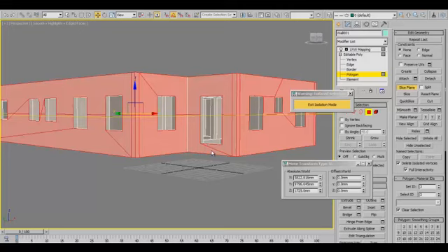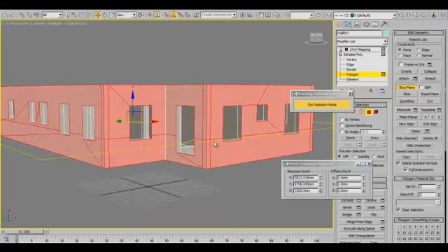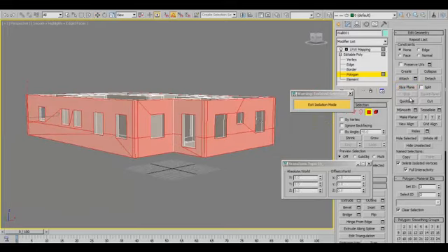This is at a 1.7 height here, so we're going to move it to 1.2, and I think that is good for us. To cut that through, because right now it's not cut through yet, we're going to click this slice, and what it does is it will actually slice at that point. So we can get rid of this by clicking this off again, because it turns on and off by clicking.